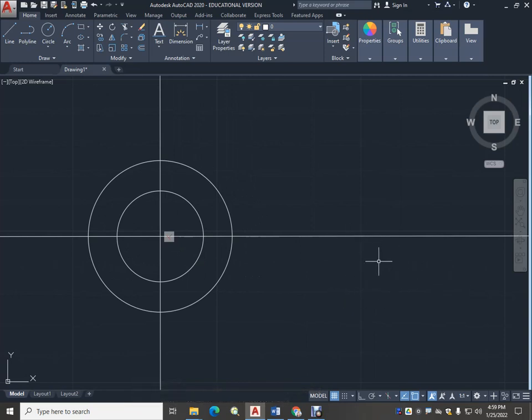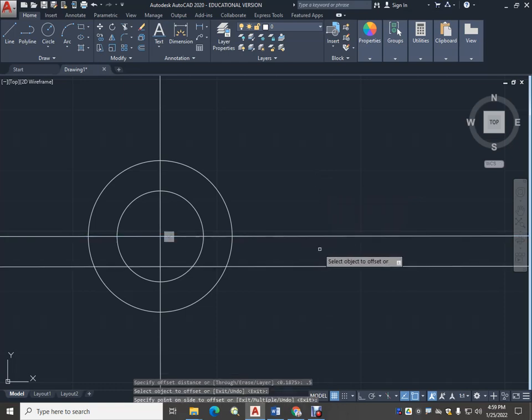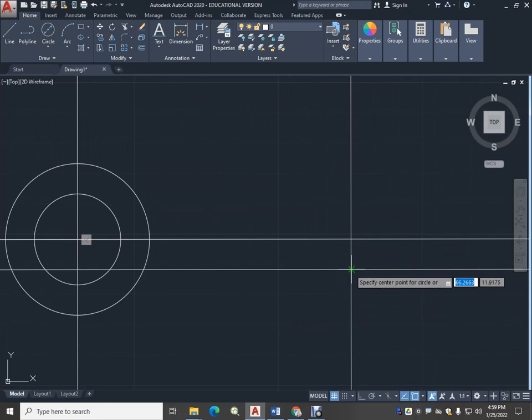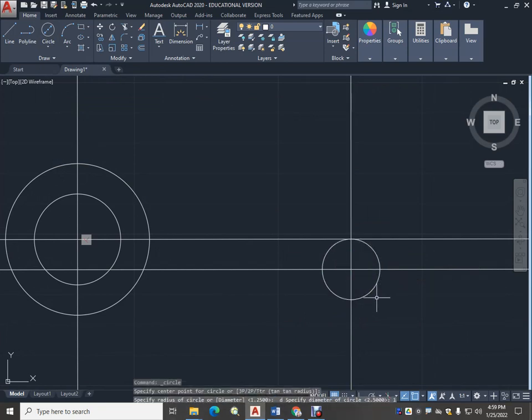Now we have to establish another center out here just like we did before. And that one is just below this center. It's a 1/2 inch below that. So let's just go ahead and do that one first, 0.5. And then it's 4 3/4 from this one, so 4.75. So we'll establish that circle, and that happens to be a 1 inch diameter. So there you have it.